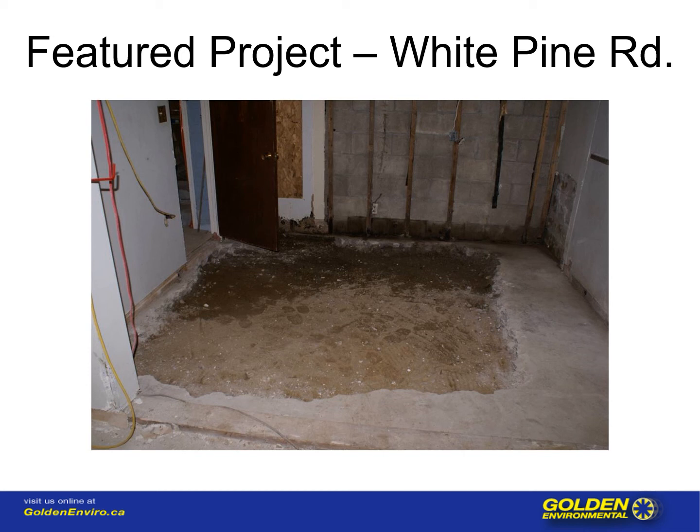However, as we were using microbes and going through the winter time, opening up the concrete floor allowed for great access to do injections as well as to aerate the soil. Remember, with bioremediation, the majority of bioremedial microbes are aerobic and therefore need oxygen.